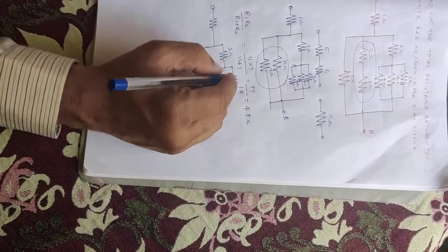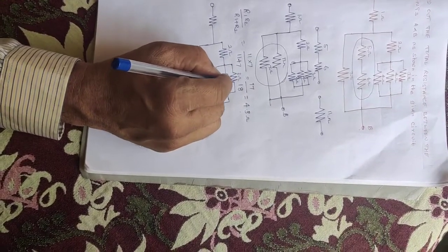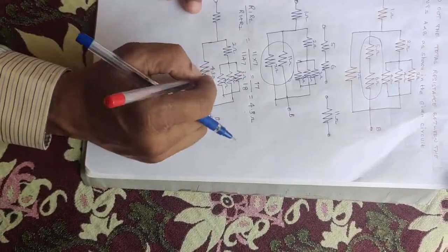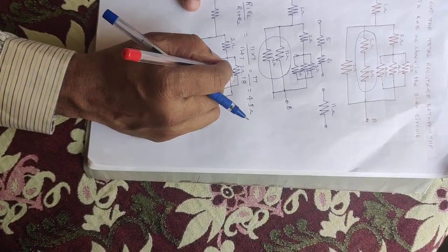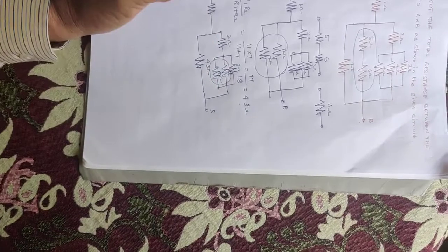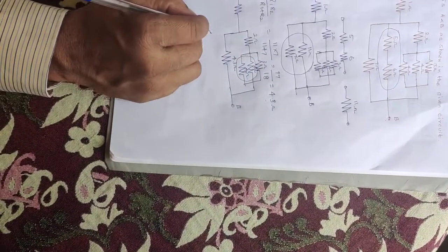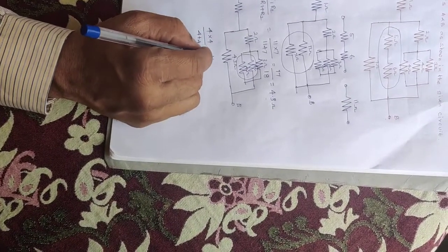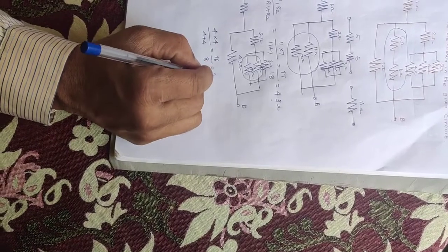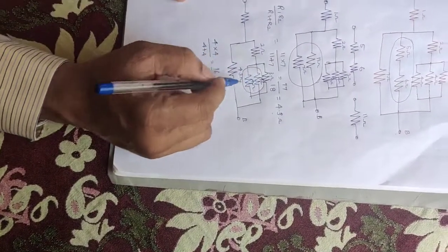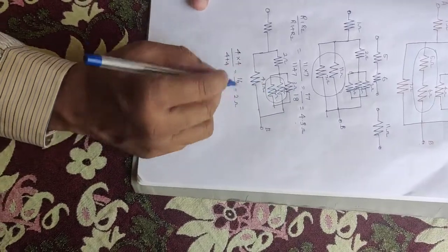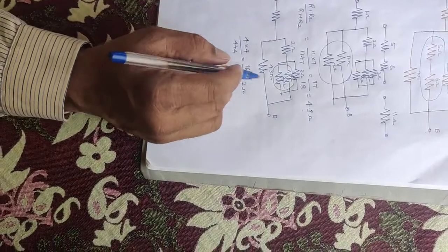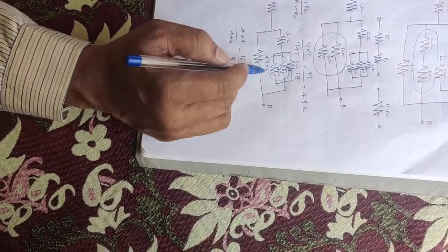Now this is 2 ohm and 3 ohms, 4 ohms and 4 ohms. Again, take these three resistors in parallel. First I am going to take this 4 and 4 ohm, using the formula 4 into 4 divided by 4 plus 4. So 16 divided by 8, I get 2 ohms, converting these two in parallel into a single resistance of 2 ohms. Now I replace it in the main circuit, so 2 ohm and 3 ohms are in parallel.